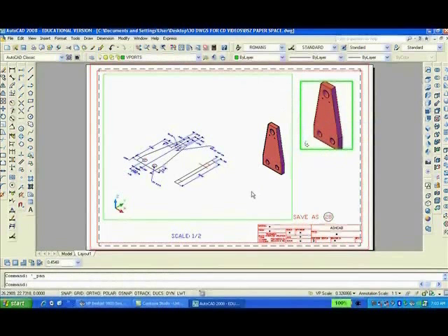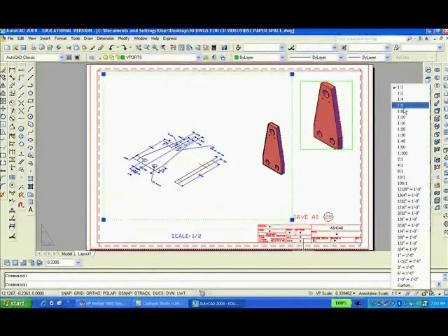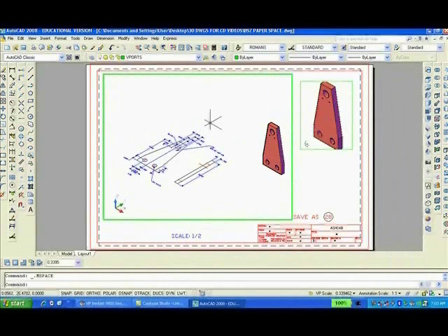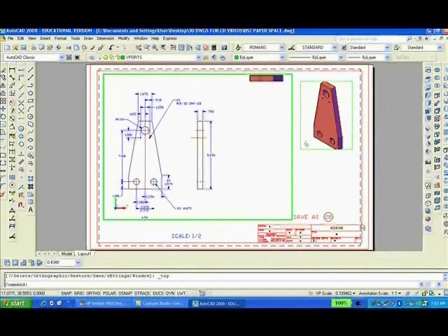And here we go, double click outside, select the 2D viewport for annotation scale, and this is going to be at 1/2. Well, first of all, I suppose I ought to go into top view, and now click outside.